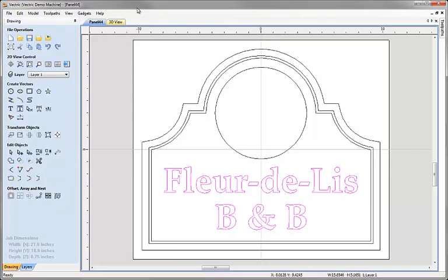At this stage, we've finished our 2D layout and we're ready to start calculating our toolpaths. Now the first toolpath that I want to create is going to be to carve our 3D element that's going to fit into the circular area in our design. I can't calculate that type of 3D toolpath in VCarve Pro or Cut 2D, so I need to use an external program in order to generate that data, which I can then save and import into the program here.